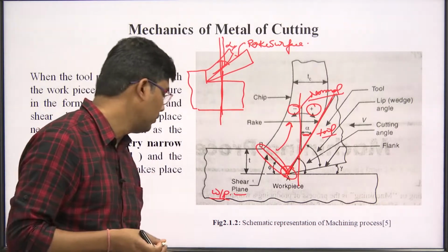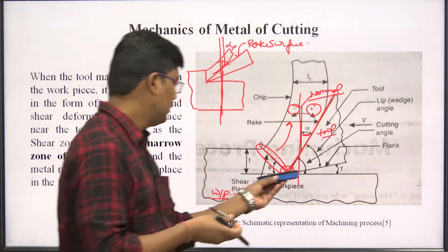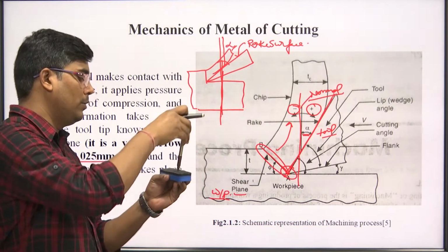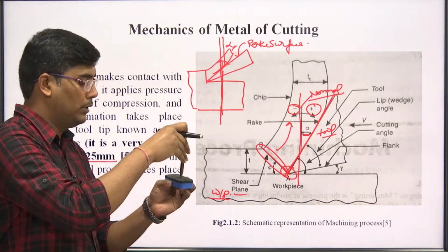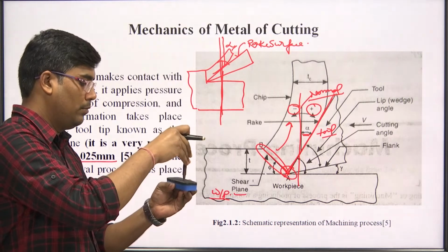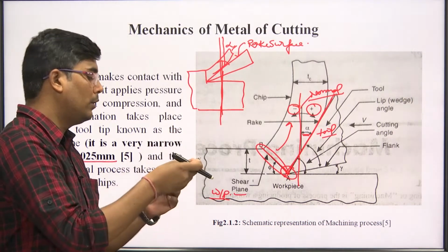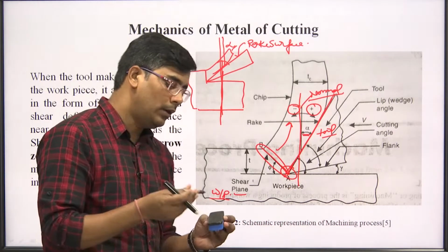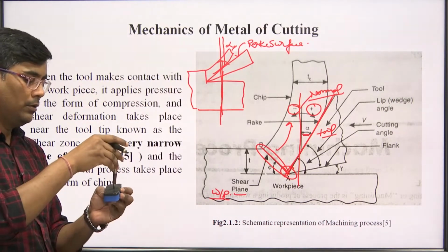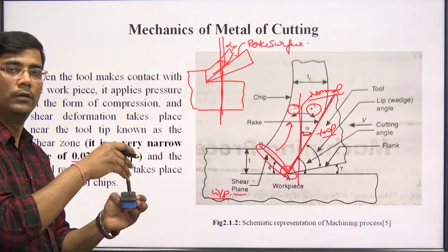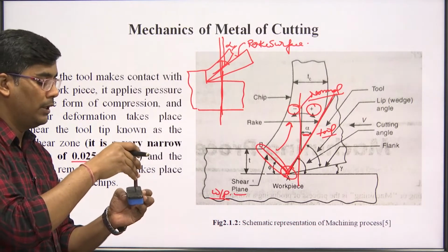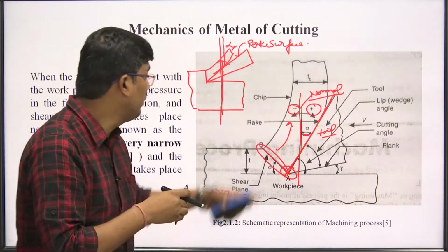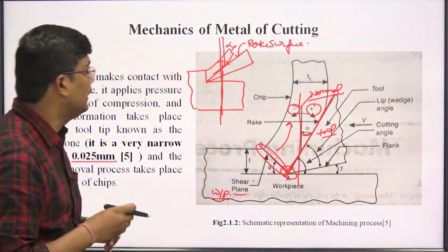आप ऐसे समझ सकते हो कि ये हमारा वर्क पीस है, ये हमारा टूल है, तो नेगेटिव की तरफ आप जैसे जाओगे तो टूल के टिप पे प्रेशर बढ़ेगा. You can see here that pressure on the tip increases and the wearing occurs at the tip of the tool. A negative angle is required when the hardness of the material is more and more cutting force is required. So, a negative rake angle will be required at that time.